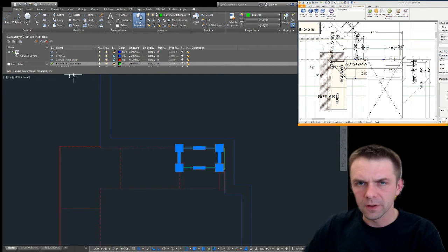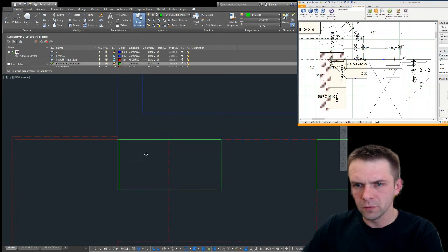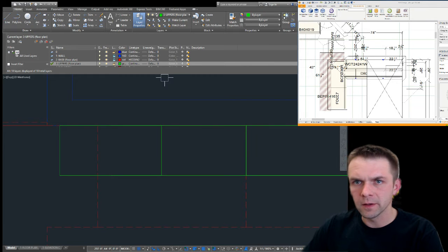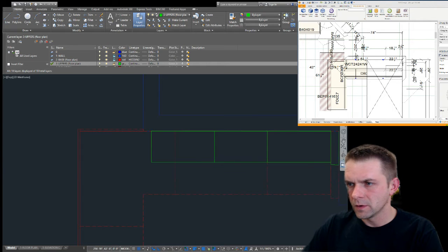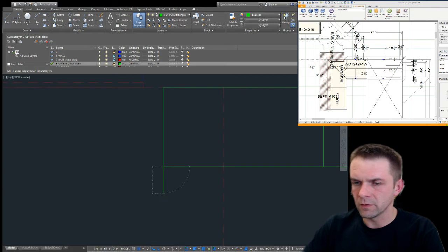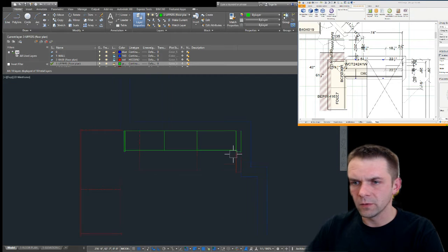So 24, we can just do copy mirror of this cabinet on the other side. So obviously we need to move it in at least 3 inches, and whatever's left is going to be our middle cabinet, and that's hopefully 20 inch. Perfect. So we also select this L 0.875, 0.75, REC space, click. So that's done. We have our upper cabinets, we have our base cabinets all figured out. Now we transfer this to elevation.